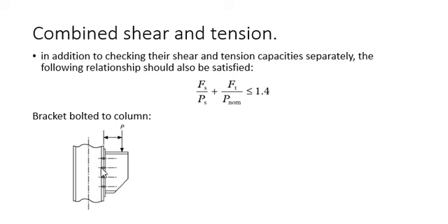Now if we take here as the center of rotation, and again this force is applied, in trying to pull this apart, this bracket would try to move out in this direction, to the right. So it means that we are having a bit of rotation here. So each of the bolts would be pulled, and being pulled means that the bolts will be in tension.